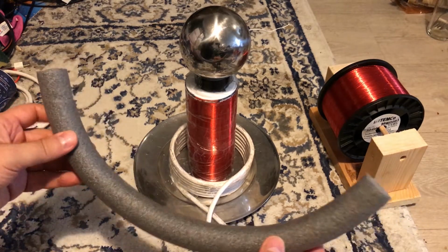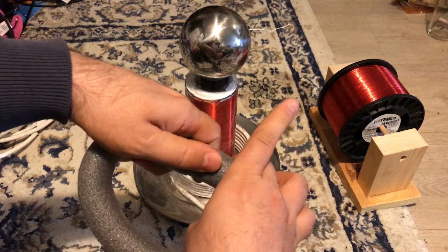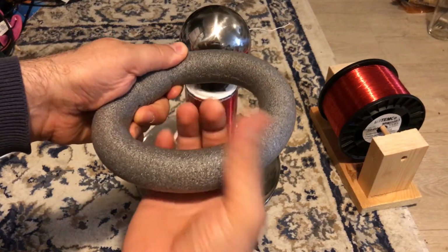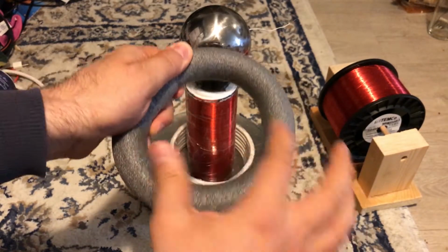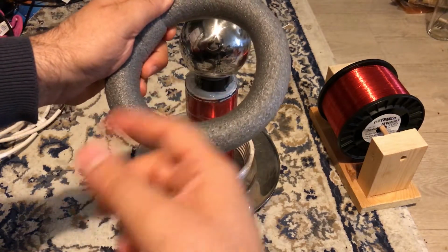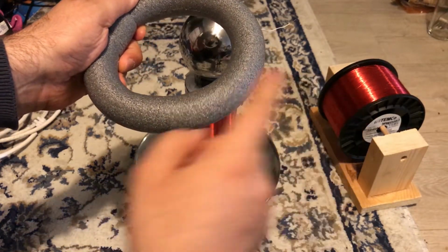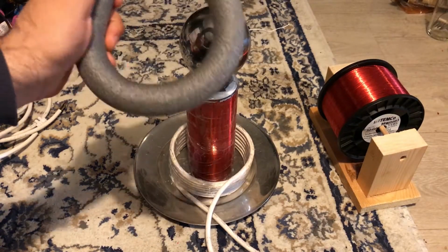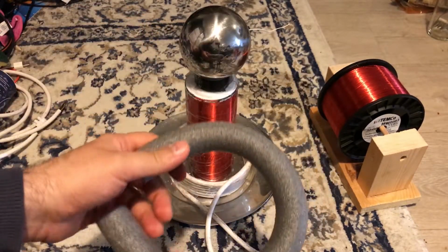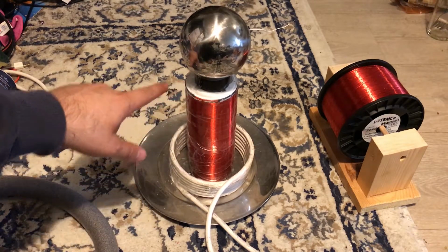I thought about making a toroid myself. That is one option. You can take a piece of foam and stick it together like this, or tape it, and then you put aluminum tape surrounding it, then it will create a toroid. And you put some kind of metallic plate in the center, so you will have a nice toroid. But even when you put aluminum tape, even if you make it smooth, there would still be sharp edges and sharp corners from which discharges can initiate. But that is one option which I will work on, and maybe if I get something nice, I will show you. But at this moment this sphere is okay, even though we know that we get some discharges from this edge.